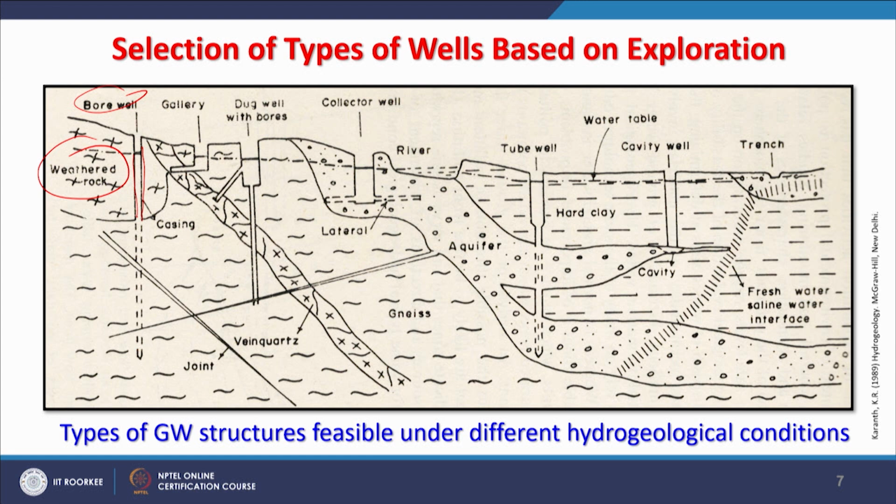So, this is one example, where the top part is weathered, and the water table is also shown here, as you can see, with the dashed line almost horizontal or almost following the topography. Now, from the groundwater recharge point of view also, galleries are there, we have mentioned galleries. So, this kind of wells can also be developed, and these wells will exploit this part which has some inclined features, and see this opening here, and you get the water in this gallery also.